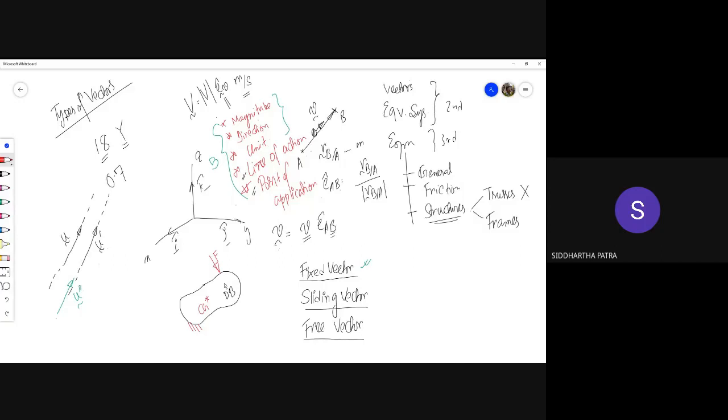And all of those would be there even on a rigid body. So what are the things that can happen? It can produce a moment about the center of gravity. What I'll do first is consider this one to be a rigid body, because its line of action is not passing through the center of gravity, it would be providing a moment. Imagine it is also not supported over here. So not only does it cause an acceleration, it would also be causing a moment about CG.